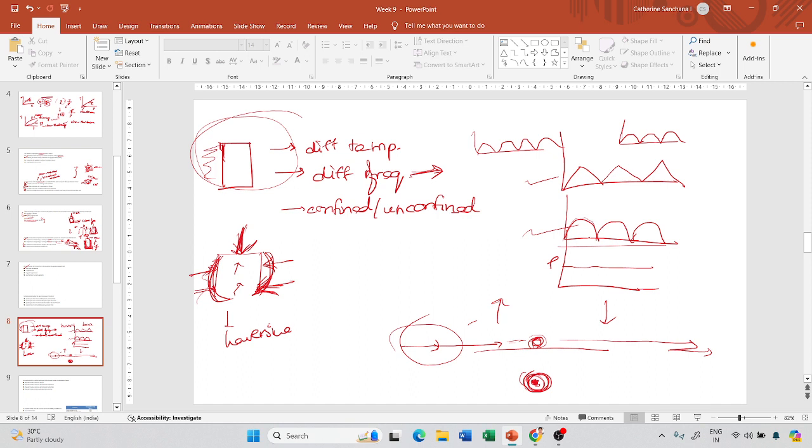Here we are going to adopt Haversine loading, and this Haversine is going to be compressive in nature, because applying tension on mixtures is difficult, right? So you are going to apply a compressive force in the form of Haversine loading on the bituminous mixture. So now how will you do this?